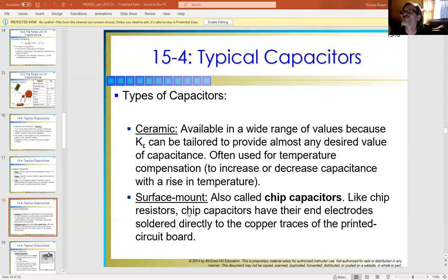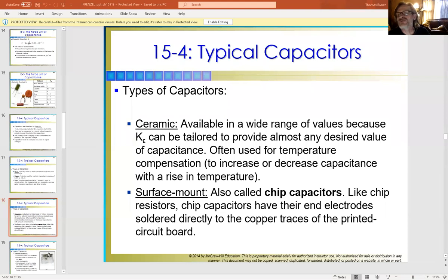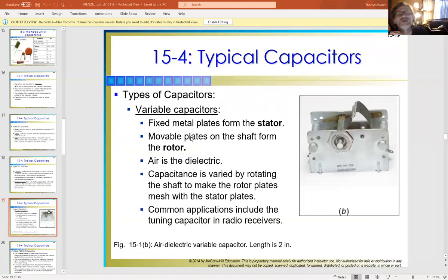SMT technology, which is more and more what we have today. It's how we got our cell phones. You open it up and all you see are these itty bitty tiny components, just surface mount, meaning that it's deposited on the board and not through. The components that we've been primarily using in the breadboard, that's through hole technology, which is the older style of electronics. But now for spacing and whatnot, we've been going to surface mount more and more. Smaller board sizes, smaller component sizes, and there's even different levels to SMT. You'll find they actually have rating numbers, and it depends on package sizes.